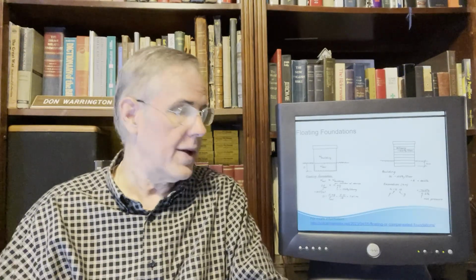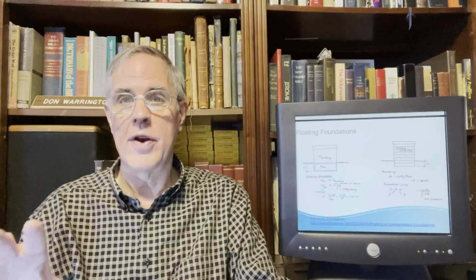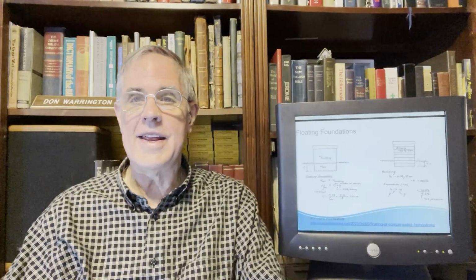If it's uniform, then we can divide both the load of the building and the area of the foundation by that area, and we have a per unit. So on the left-hand side, the D, which is the depth that the building sinks into the soil, times the, strictly speaking, he's got density there, that should be a gamma unit weight.